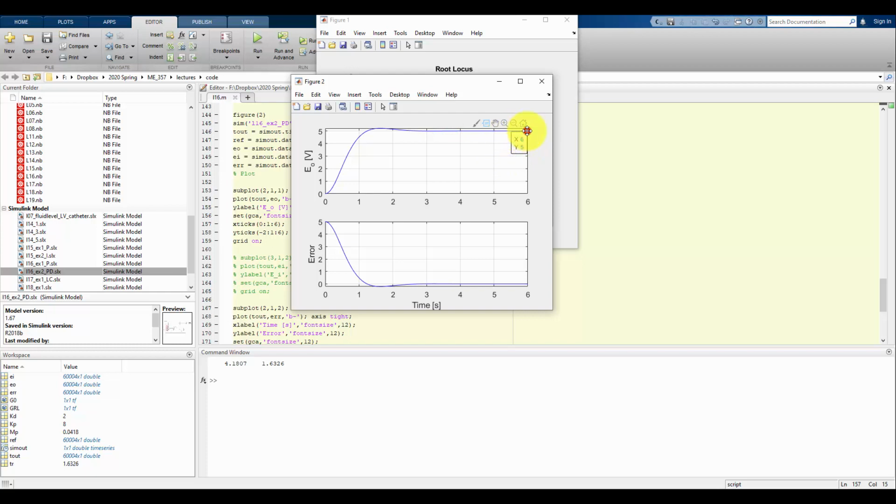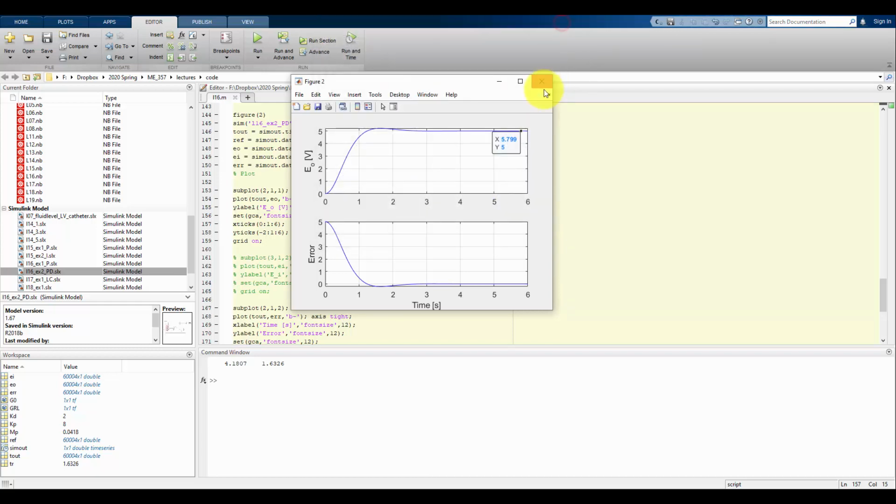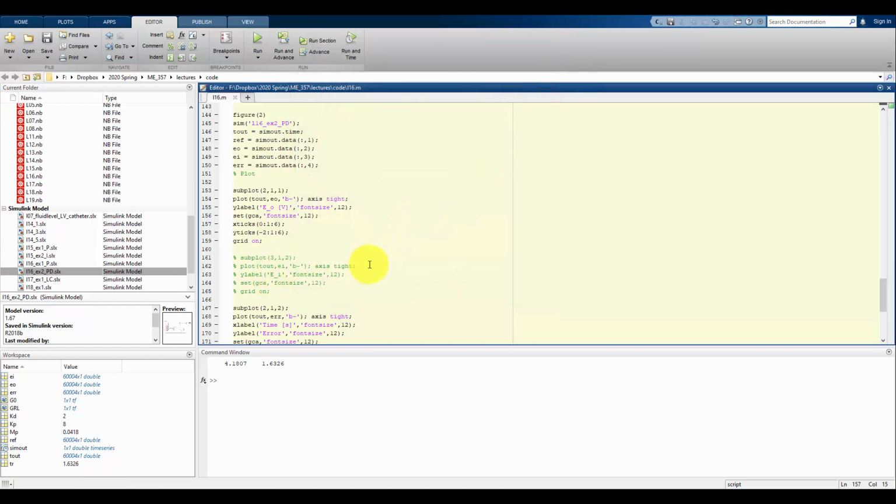And it's behaving like a second order system, or it looks like a second order system. It's not entirely because I have that extra 0. But we see here I get some peak value. I'm eyeballing it for the moment as about 5.2 as the peak value. I do have some oscillations, but then it settles down into my steady state value of 5. Now, quickly, I do want to investigate the input effort a little bit. So let me just plot that quickly so we can see what it looks like.